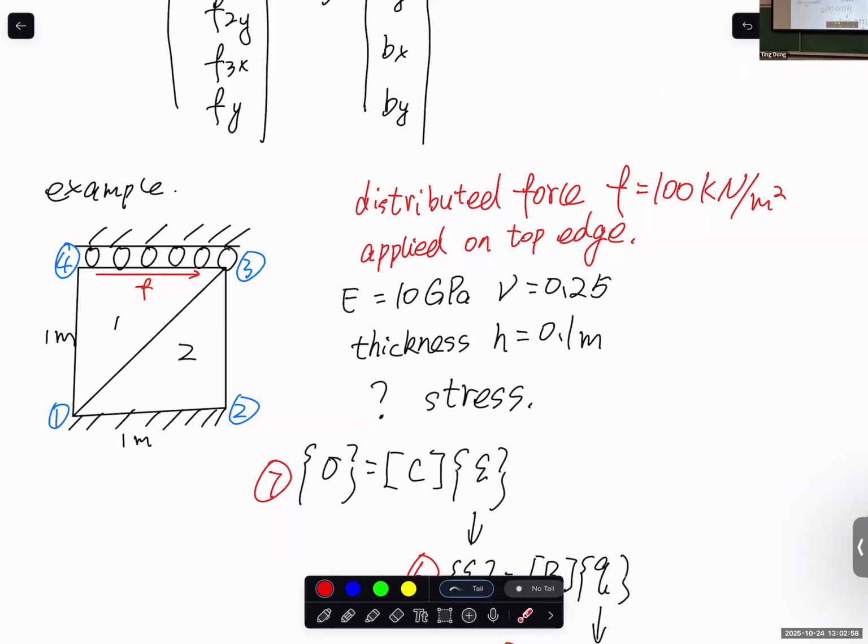There's no normal stress in X, there's no normal stress in Y. To generate normal stress in X and Y, from tension compression, let's say if this is the X-axis, I need to apply tension compression force in this direction, right? To generate normal stress in the Y direction, I need to apply tension compression in the Y direction to have epsilon YY. Or I can apply a bending to generate normal stress, right?